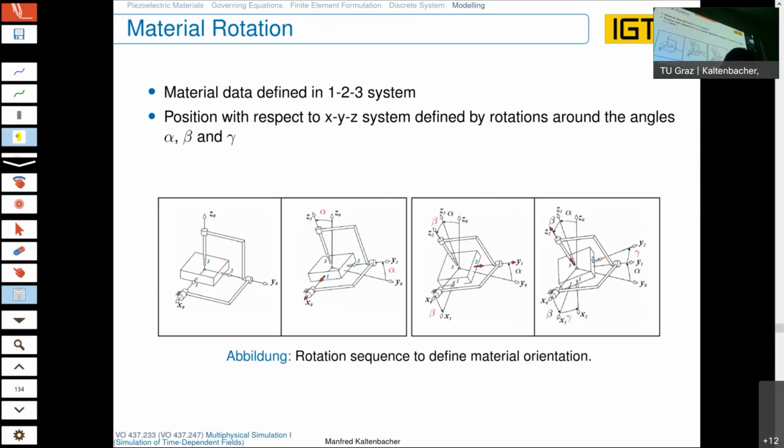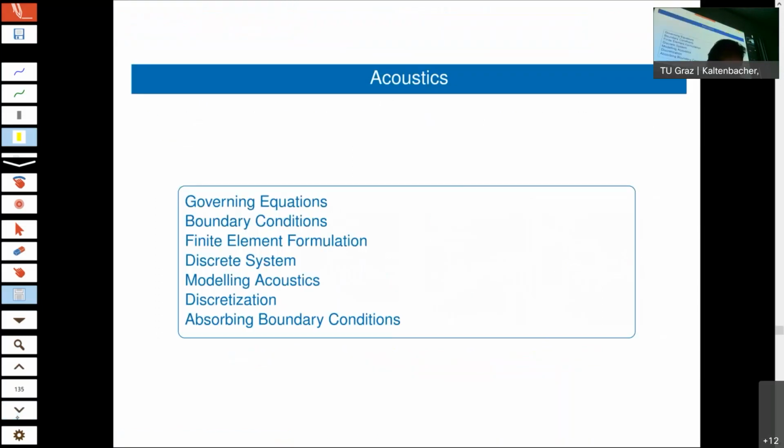As you have your material parameters, where we assume that we have the polarization in thickness direction, you have to do a rotation of your material tensors as shown here in order to do a correct computation. That will also be discussed in detail in the exercises, where you do additional commands in your XML file.